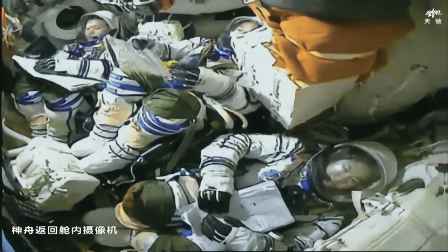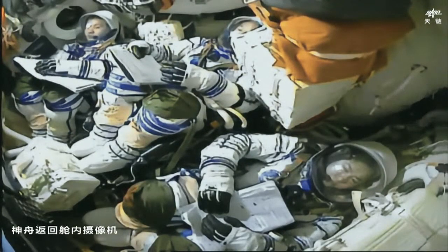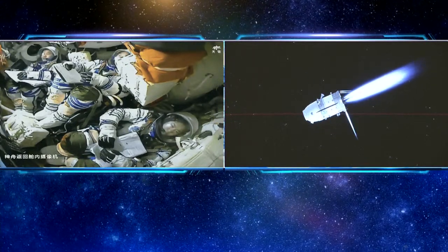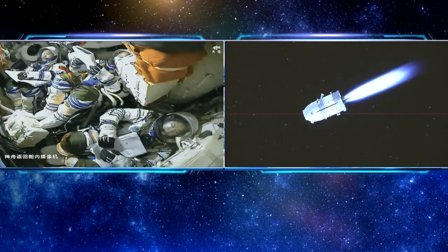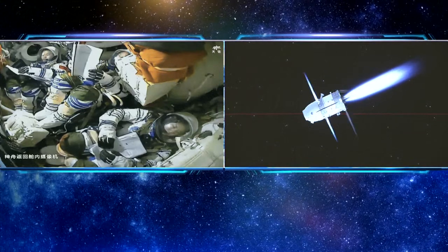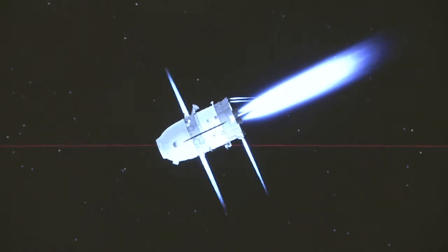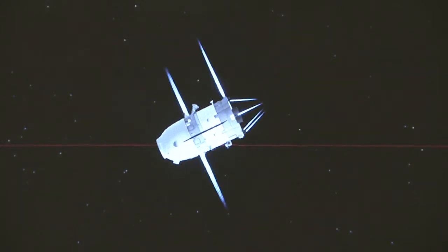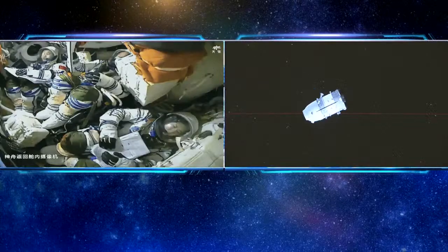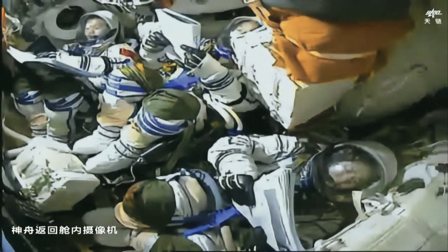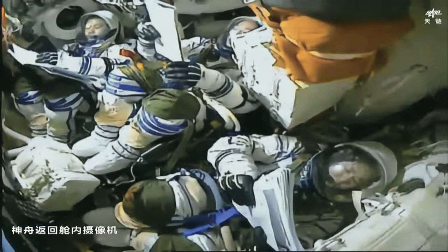As we just reported about 5 minutes ago, the capsule has finished at least 2 adjustments of its attitude. Why exactly is this so necessary? You know that our Shenzhou spaceship has a 3-module design. The first step is the separation of the orbital module, as your colleague already mentioned in the Beijing Flight Control Center. This is to reduce the total mass of the spaceship. But to avoid any collision, we must separate in a different direction. That is why we conduct the first attitude maneuver of about 90 degrees. And then for the deceleration, we must use the main engine on the propulsion module, like we see in the 3D animation now. So this needs another attitude maneuver to change the direction to the right one. And as we have already seen from this video, according to the commander on the ground, the de-orbit maneuver has been successfully conducted. Now, at this moment, the Shenzhou spaceship is on the trajectory back to the Earth.